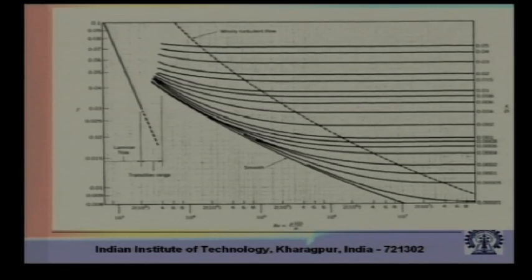Now, what is on the vertical axis on the left is the friction factor, that is your output from this diagram, which you want to utilize for estimating the head loss. For low Reynolds number, you have to keep in mind that f equals 64 by Reynolds number. So if you take a log, then in the log plane it is like a straight line coming downwards. That is what you see for the laminar flow. Now suddenly, beyond the critical Reynolds number, which for a pipe flow is roughly close to 2000 or so, you see that the friction factor jumps up. That is the first observation.